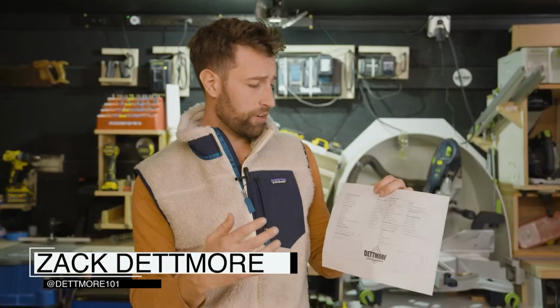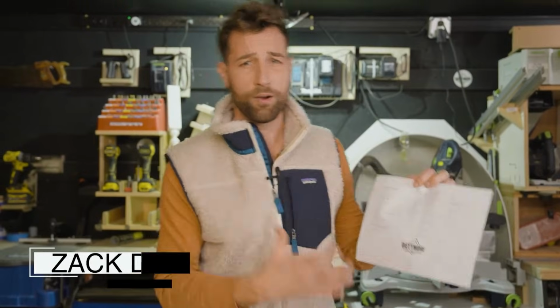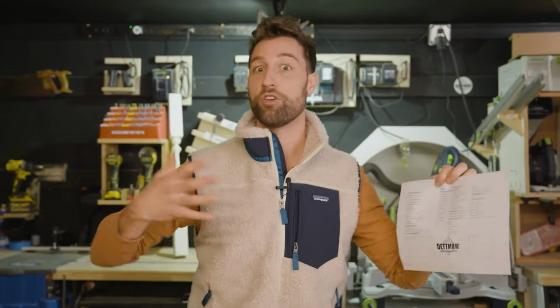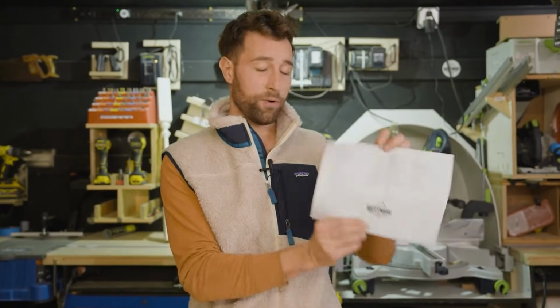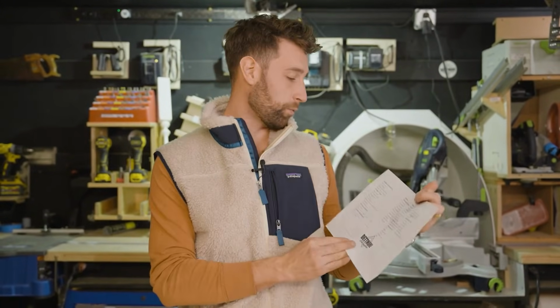So we start with the first thing. The reason you want to get windows ordered correctly the first time is because there's a huge lead time for windows, and if you have it wrong, that can totally hijack your exterior package, your interior trim package. It can throw the whole schedule out, so you do want to take the time to get this done correctly. So let's talk about just ordering one window with one piece of sheet. We're going to work this through together.